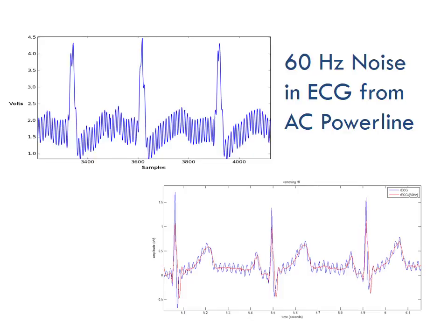Remember, the AC power oscillates at 60 hertz. It oscillates 60 times per second. That's the predefined measure that we've picked and standardized in the US. If you go over to Europe, it's 50 hertz, so slightly different waves. So a lot of the filters that you use for this kind of thing have to be tuned to your location to make sure that you have the correct filter for the correct location. A lot of filtering electronics, and actually a lot of electronics in general, will not work if you pull them directly from Europe over to the US or back and forth.